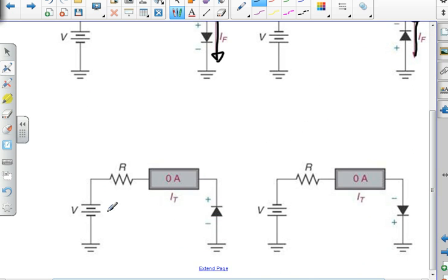I look at this guy, I'm positive, I'm reverse biased. I can spell bias, and there's no current flowing. I'm reverse biased. There's no current flowing. Zero current is going through my meter. If I have a really good meter that can get down to nanoamps, yeah, I'm going to see a little current, but that's none. That's no current.